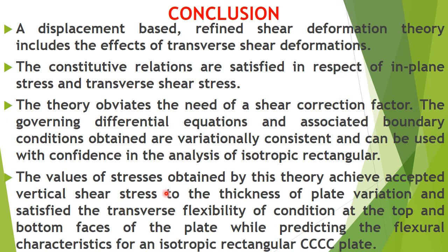So the value of stresses obtained by this theory achieves acceptable variation of shear stress through the thickness of the plate, and this satisfies the transverse shear stress-free condition at the top and bottom faces of the plate, while predicting the flexural characteristics of a plate with this